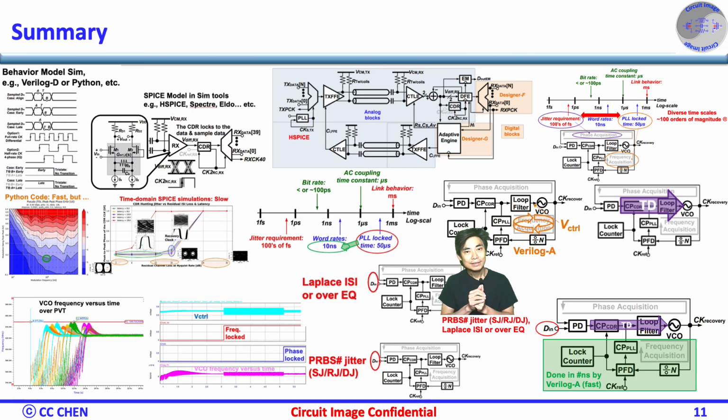When combined, these techniques give us a powerful simulation platform. It's fast, accurate, and modular, ideal for verifying bang-bang CDR across all PVT corners. Efficient simulation isn't just nice, it's essential for modern CDR design and even top-level studies.